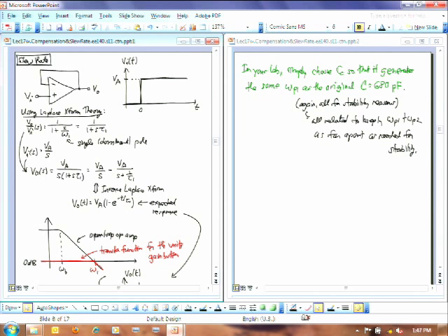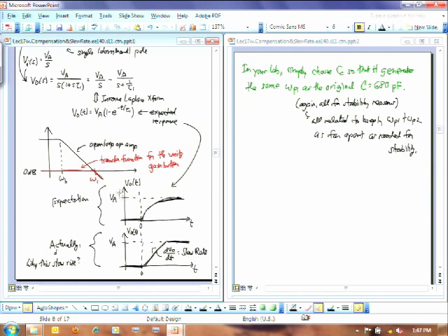And so I've got a couple other things here. In this buffer circuit here, if this black is the open loop op-amp response, then the red here is the closed loop response once I hook it into the buffer circuit. Once I hook it into this, it becomes unity gain. Unity gain is 0 dB, so I stretch this across. I get a new 3 dB frequency that's omega 1 here. We sort of talked about this in the last lecture too, how we do this.